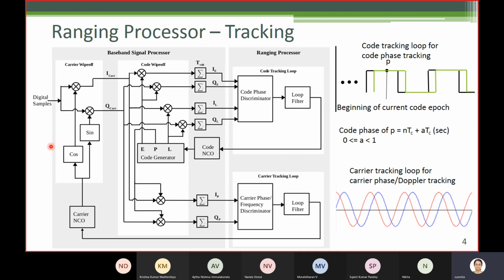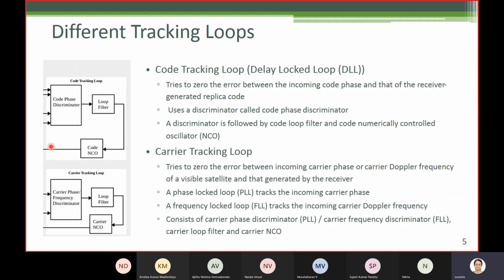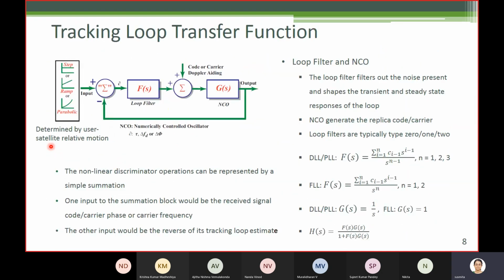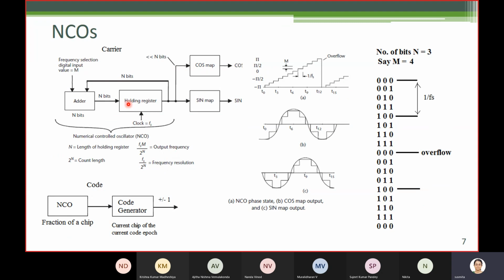So basically, we do not require anything more than few megahertz plus minus few kilohertz. That is what we want. And it lies well within the range that the carrier NCO can generate with say 200 megahertz clock and 32 bits or 64 bits adder.